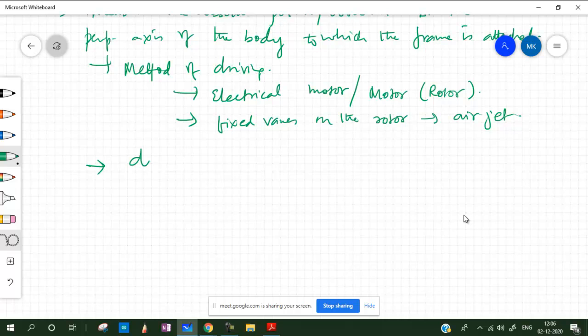So we do have something called as drift. जैसे हमने पढ़ा था zero drift या sensitivity drift. What happens is because of the friction, which we cannot generally avoid, we may make things quite fine, but still there is some amount of friction in the bearings and maybe in the whole connection between the gimbals and the frames. We have bearings, so we do have some sort of friction there. Because of this, we have some phenomenon called drift that happens there,